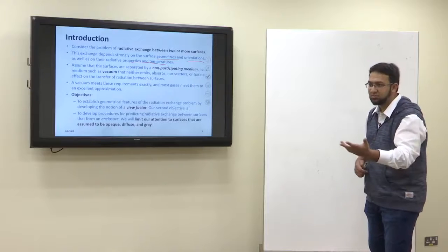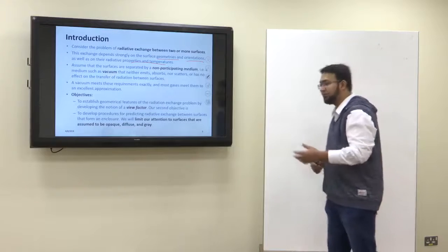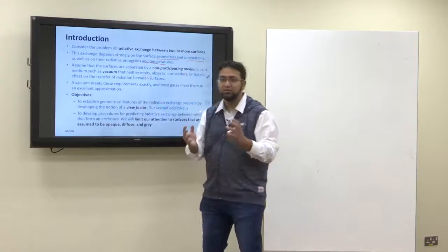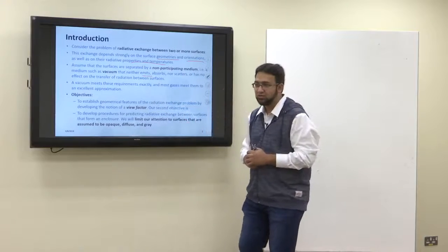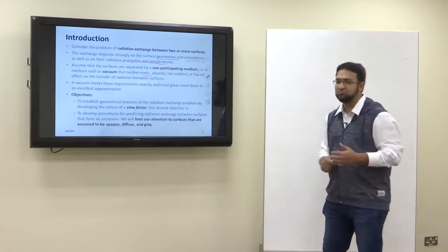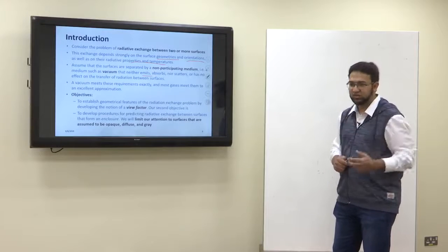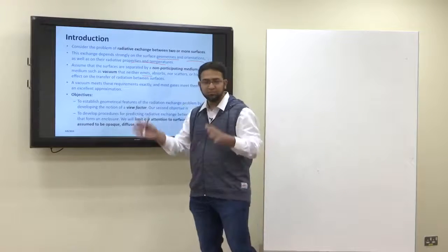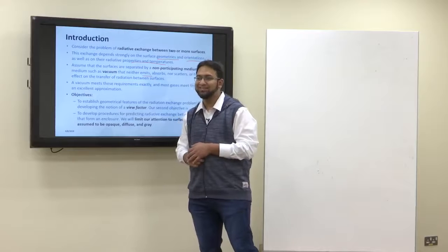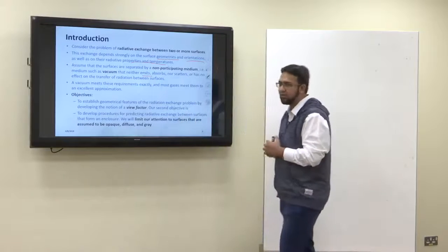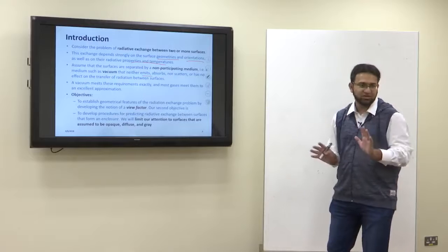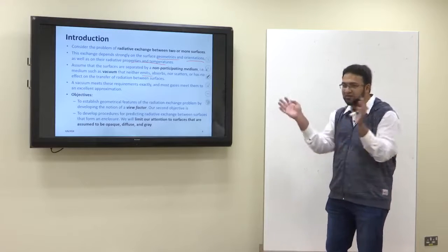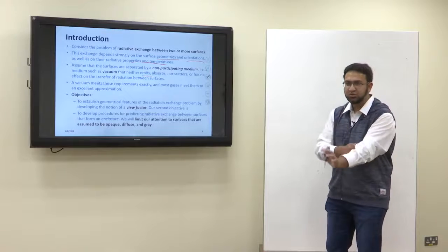It is absorbing some amount. Or if the in-between medium emits radiation, then the radiations will be increased. Okay, so that's producing a disturbance in the radiation transfer. So what we assume is that the medium in which radiation heat transfer is occurring is non-participating. It does not do anything to the radiation: it neither absorbs it, nor emits radiations, nor scatters it, nor changes the direction. It's not like that.